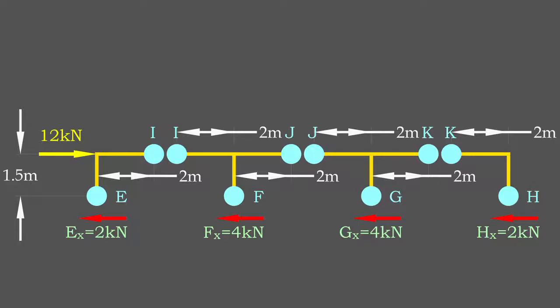After determining the column shear force, we can dismantle the frame at column and girder hinges. We first analyze the part that receives the lateral load. Using 3 available equilibrium equations, we can determine the remaining 3 unknown forces in hinges at this part.